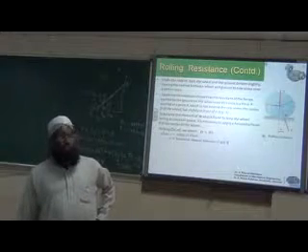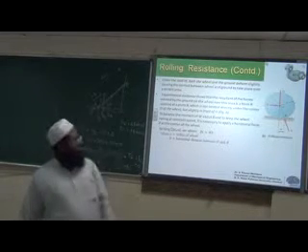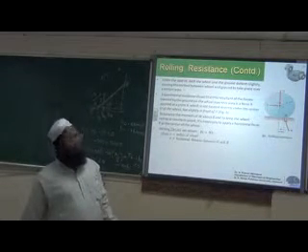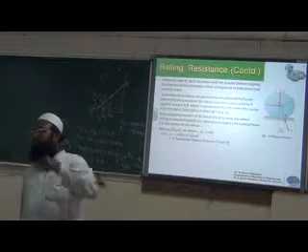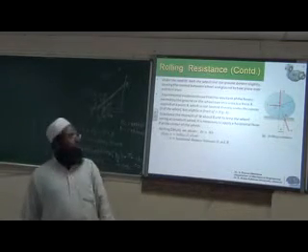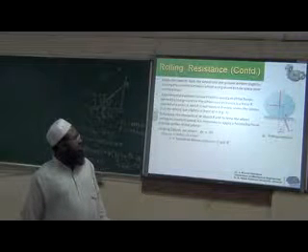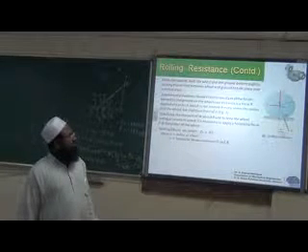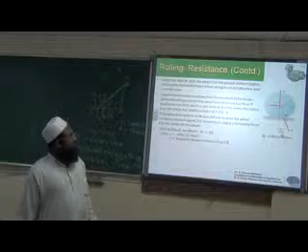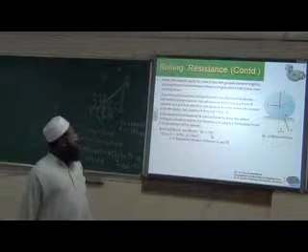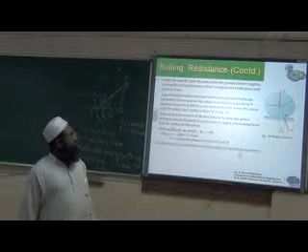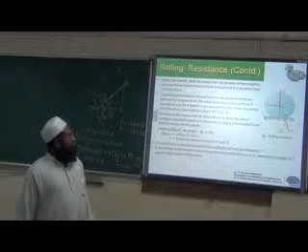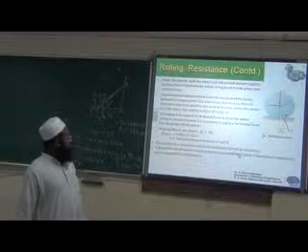Okay, so we have a deformation at the junction due to weight, so the resultant of all the forces, due to the deformation the wheel cannot move; we have to apply some force, then only the wheel will move. So we apply some force, and accordingly we get a reaction force. The reaction force is tilted at some angle, and it lies at some distance from W. So this distance B is called rolling resistance. The distance B is generally called the coefficient of rolling resistance. So this is about the rolling resistance.